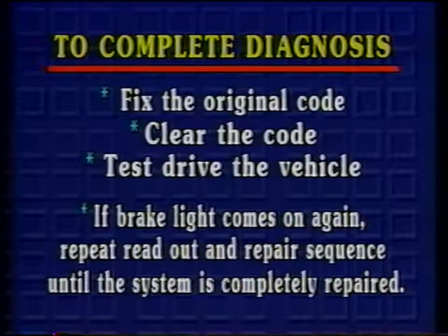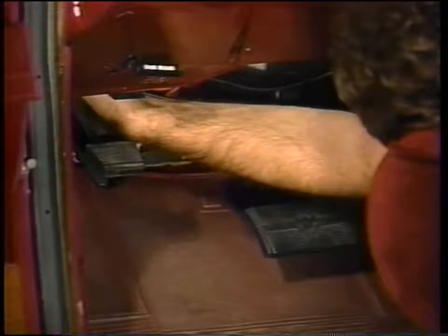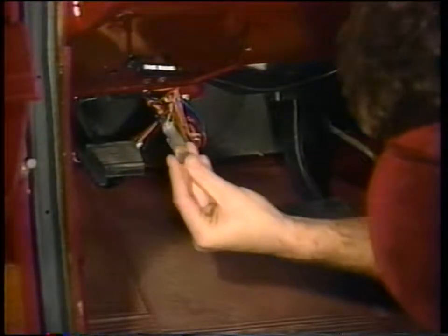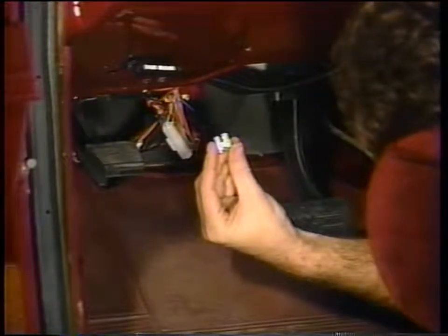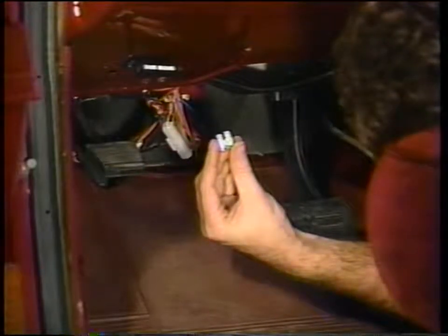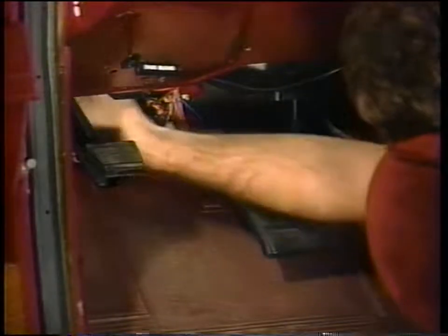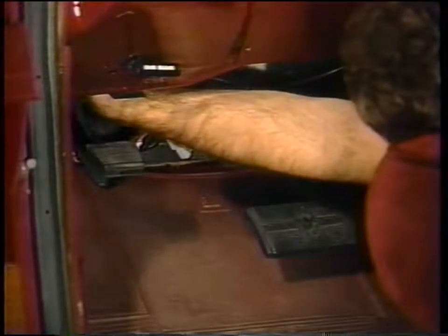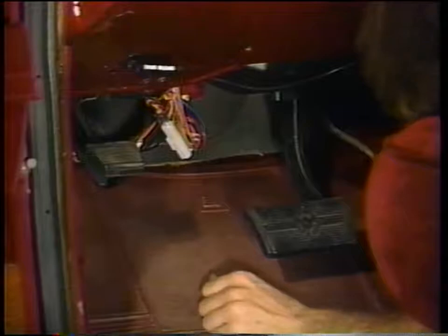To manually clear a stored fault code on GM and some Dodge trucks with RWAL, remove the appropriate fuse or disconnect the battery for 5 seconds. Codes will clear once the ignition is turned to the off position.